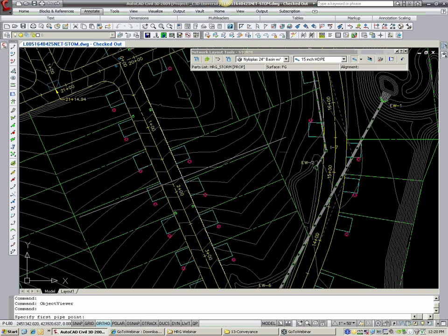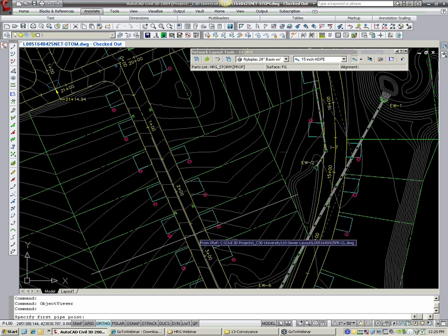That's the way I need to connect these inlets, in the downstream direction. So my workflow recommendation for everybody is place your inlets throughout residential or commercial. Get them placed. Determine your low spots. Get them all placed. After it's placed and it's time to do your conveyance design, then come back and connect